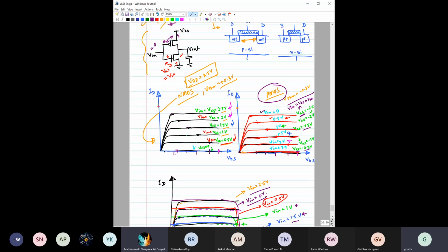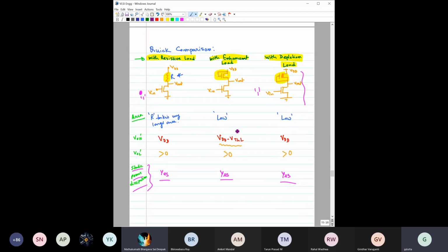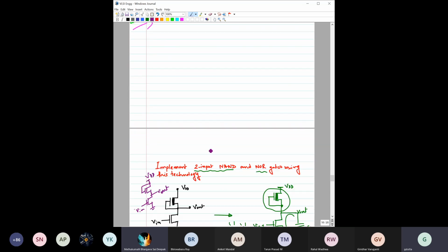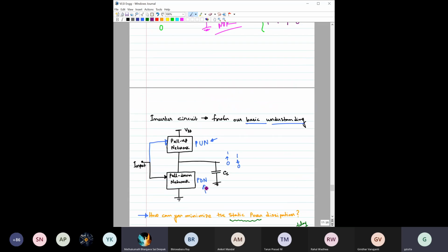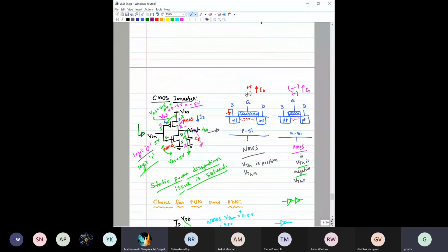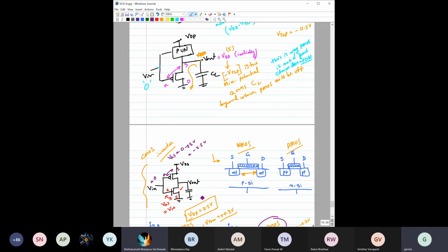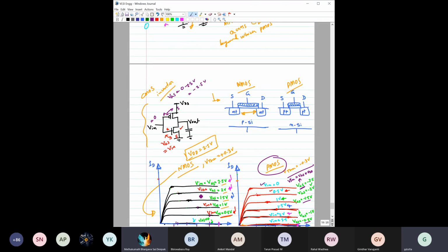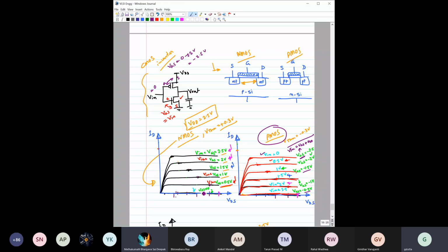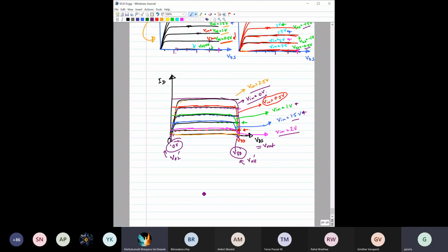What are the other drawbacks that we have seen in the earlier case, right? The area requirement, again, that is not an issue, because we are using only transistors, right? So there is no resistance part. So the area requirement criteria is also fulfilled. So as you can see, then why is this CMOS so popular for making digital ICs? Because of this reason, right? By using this type of circuit, we can overcome so many difficulties that we have seen in earlier cases, right?